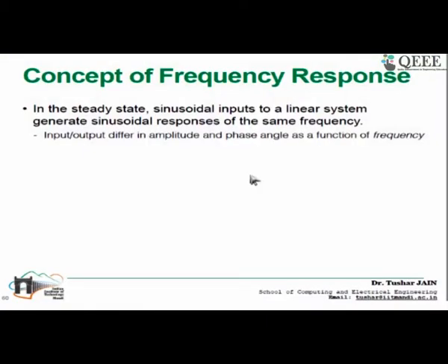Okay, so we'll start with our frequency response. What do we mean by the frequency response, and how is it different from the other methods we have discussed so far? Since we are concerned about the steady state, about the equilibrium points, when we apply a sinusoidal input to a linear system, it generates a sinusoidal response of the same frequency. What differs between the input and output is basically the magnitude and the phase angle,